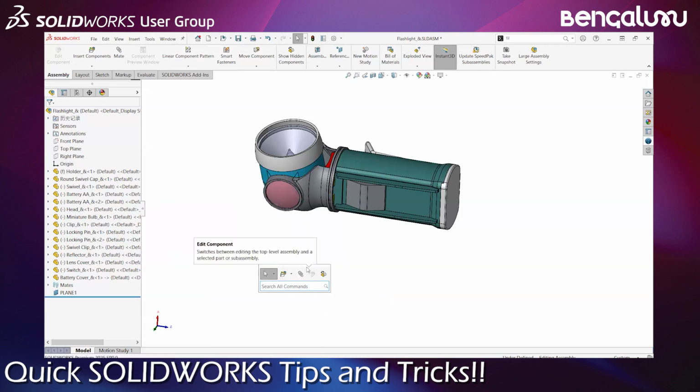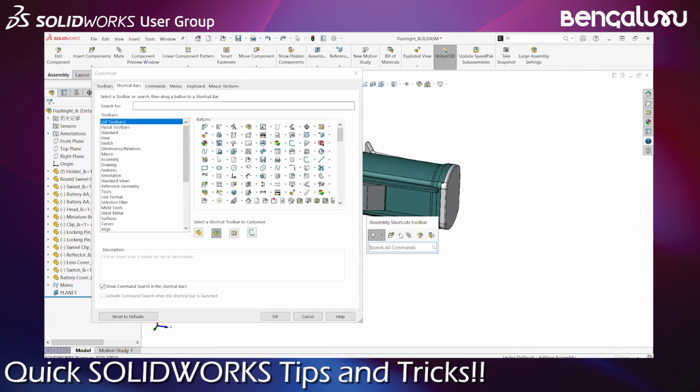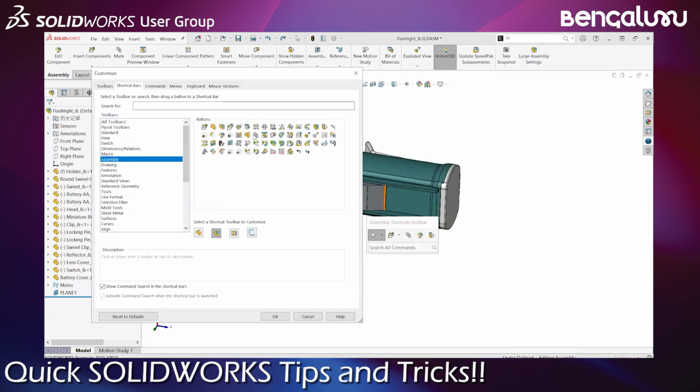For example, I'm in an assembly environment right now, so I can right click on this and say Customize, or I think you can even access it from here. But I right click and say Customize. When you hit Customize, you can see the assembly shortcut bar, because you are in an assembly environment, and you can add whatever commands you need, not only from assembly, but whatever commands you need. You can just drag and drop them.